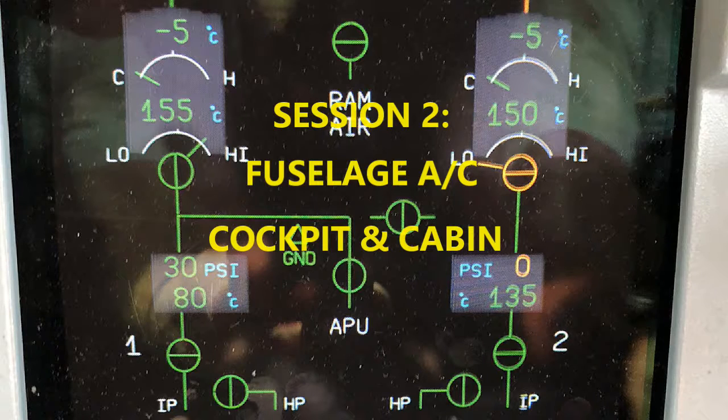Okay, so let's go over pack control. Your air conditioning packs, I just described the components that we'll get into, but we also have pack control. So we have zone control for the zones, and we also have pack controllers for each of the air conditioning packs. The controllers actually have two computers just like the zone controller, because we want to have a backup, right? So you have your primary and secondary with the pack controllers.